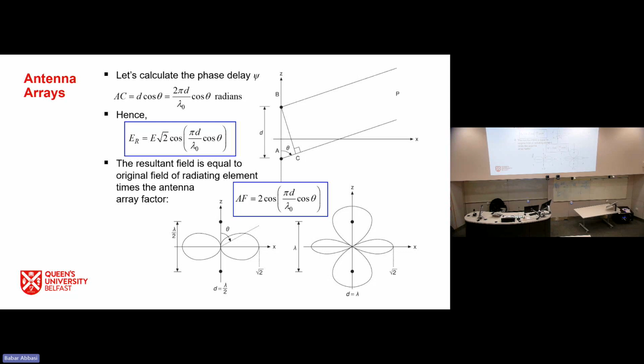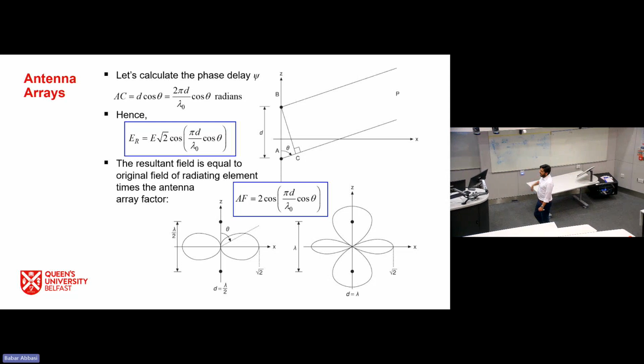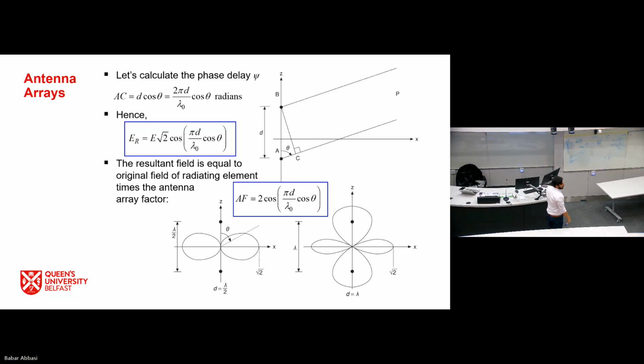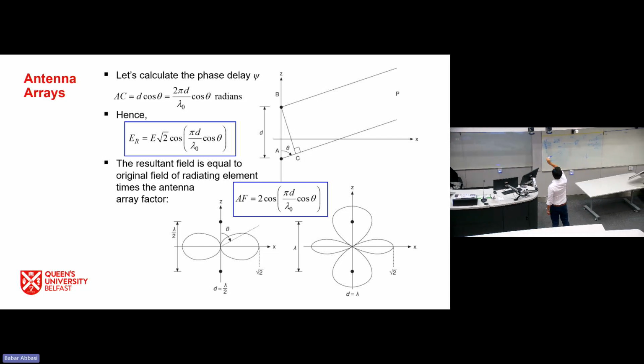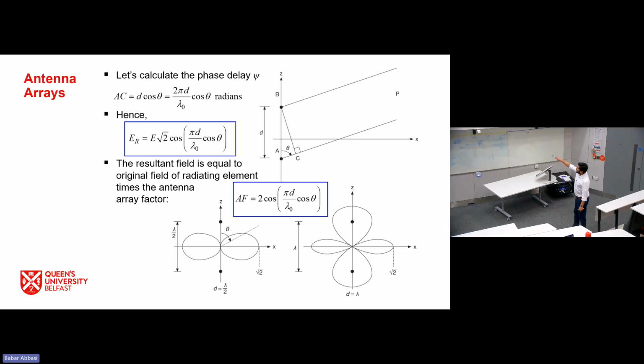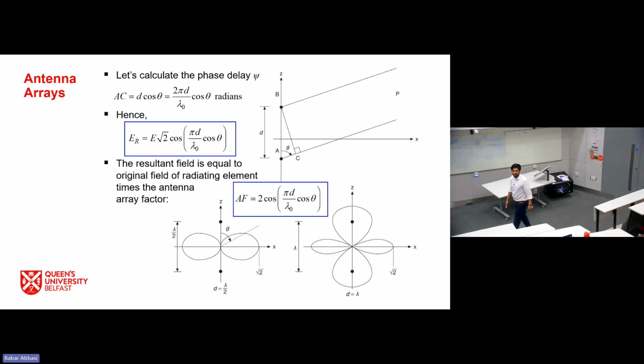are giving. Okay, so if I have simple two antenna elements placed at half wavelength distance, then their radiation will look something like this. So maximum direction is under root 2 in these two directions. And if I have these two antennas, or point sources, placed at a distance of lambda, then my radiation pattern, or solution of this array factor equation, will be something like this. Okay, so now it has 4 nulls and then 2 maximum directions of radiation.